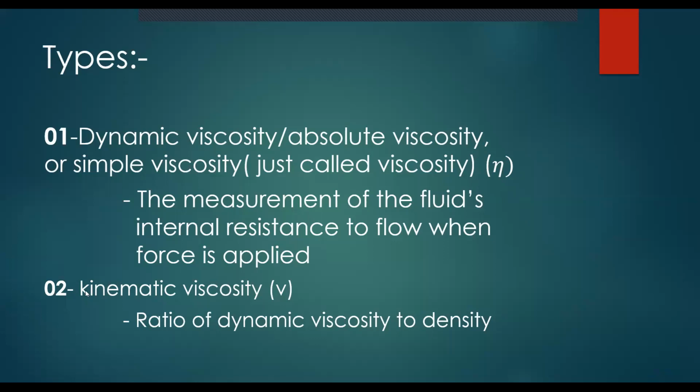Here the difference is we divide this viscosity by the density of the fluid, and that will be the kinematic viscosity. Only these two are the main difference, right? Two types of viscosity you should know: dynamic, or just viscosity, also called absolute viscosity, and kinematic viscosity.